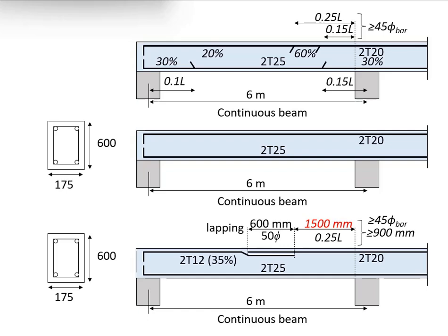Then you can guarantee full stress of the bar is effectively transferred. Since now the smaller bar size will govern the capacity, you will only need to provide the amount of lapping length sufficient to generate full stress for the smaller bar size. Beyond that, it will be a waste. You can actually provide more in accordance to the bigger bar size. Just that later, the lapping will not fail, but the smaller bar size will fail.